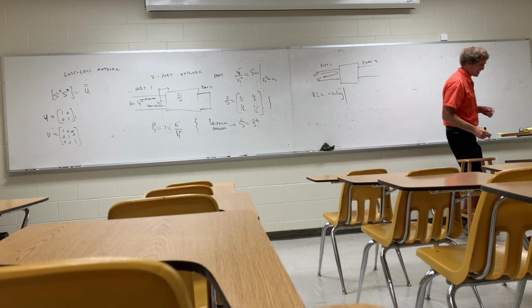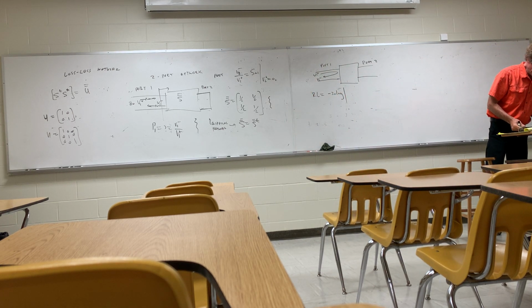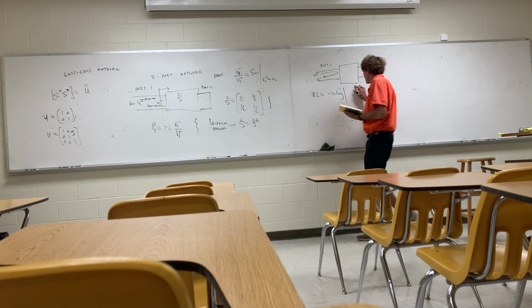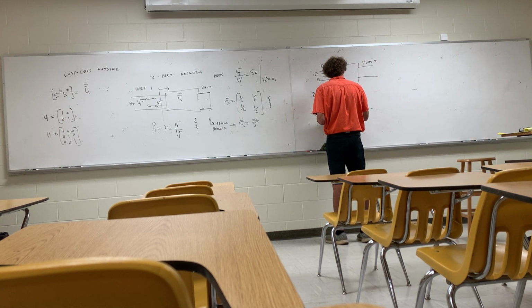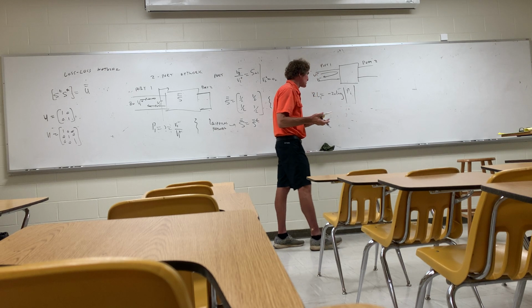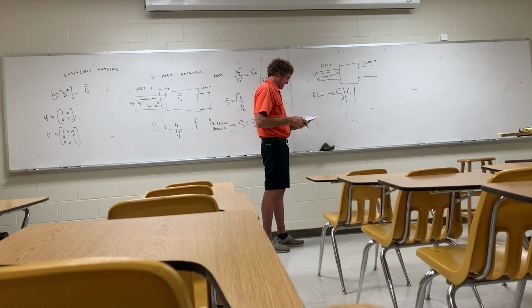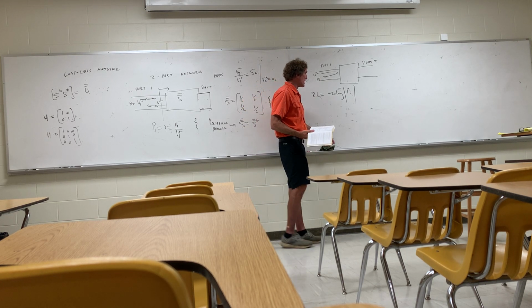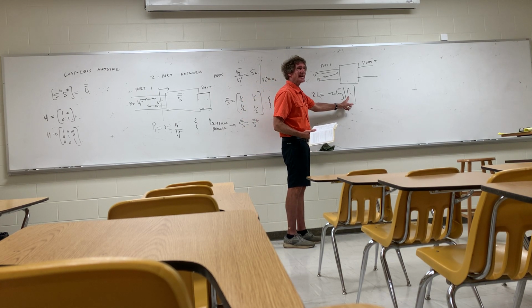In his book, he uses the reflection coefficient at the port. So the return loss for whatever port it is is equal to minus 20 times the log of the reflection coefficient. I want to mention something. The way I think about this, that reflection coefficient is S11, or it's S22, or it's S33. Y'all follow me?